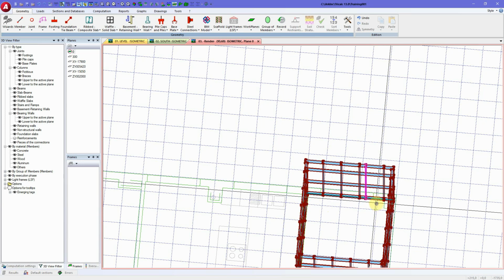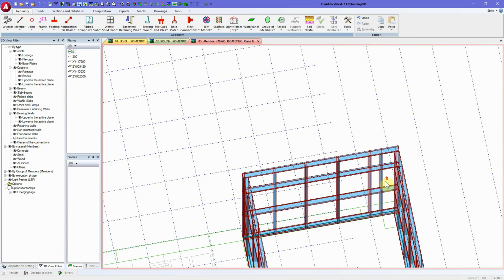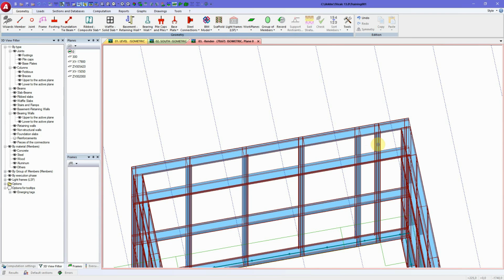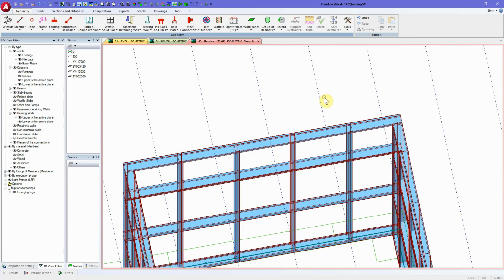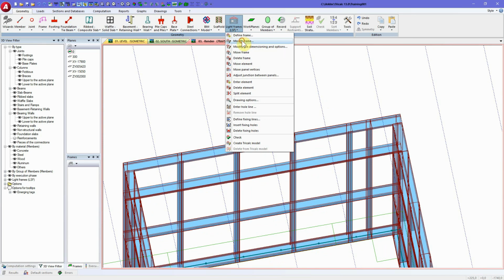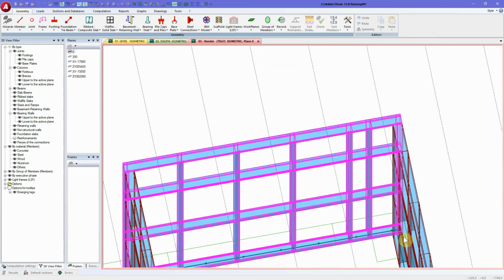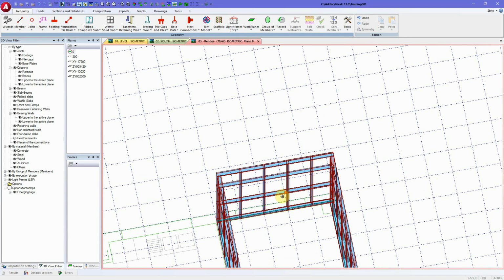In this case, I see no need for the existence of that point, that post over there. So I would like to delete it. I can make that deletion in two ways. I can just delete the element and graphically do that operation. It is done. I'm going to undo. Or we could modify the panel here, and we can delete it here. Delete the vertical bar. So in this case, we made the change inside this wizard, this assistant. The same result.